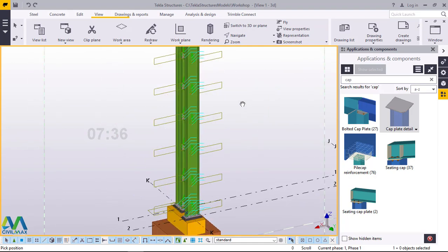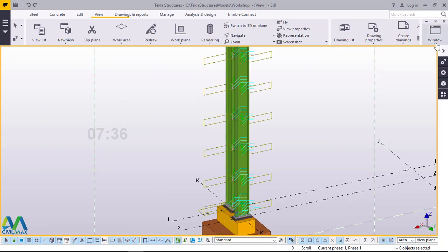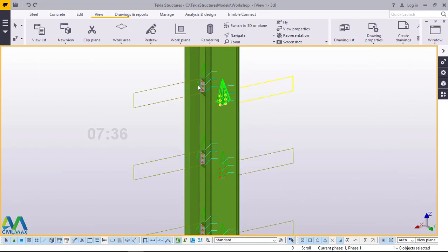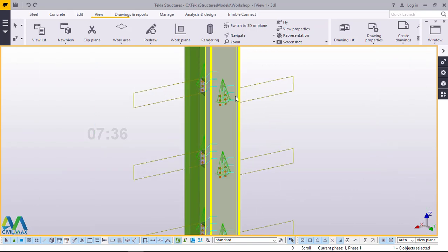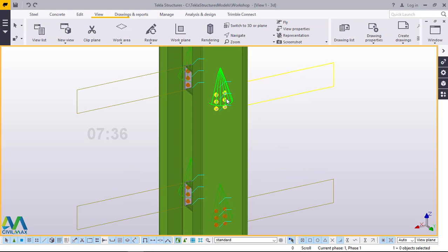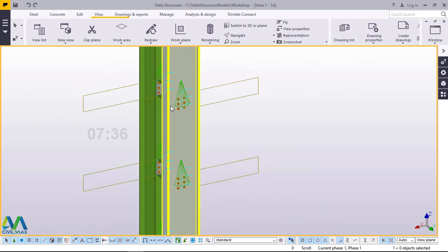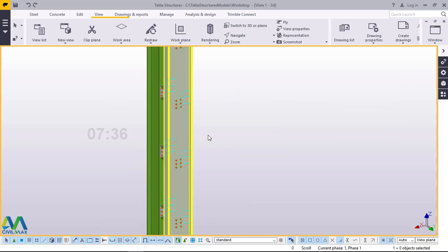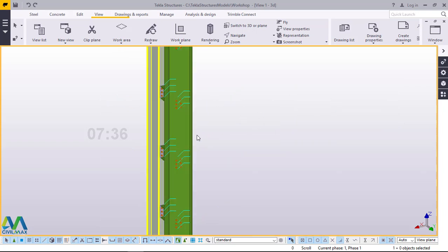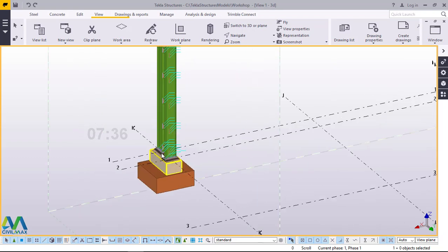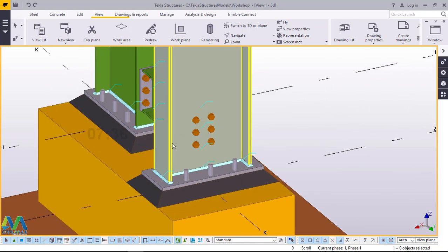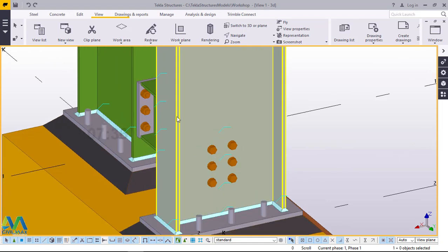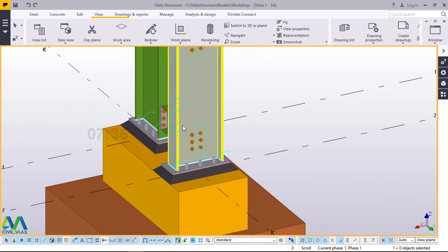Now from here, what we're going to do next, we'll shift back to our elevation or grid K. Now prior to doing that, we want to remove all these macro active symbols. I'll right click and come to redraw here and refresh. The moment you refresh, all this will disappear, and it will leave you with a clean work of these columns connected, creating for us a compound column.